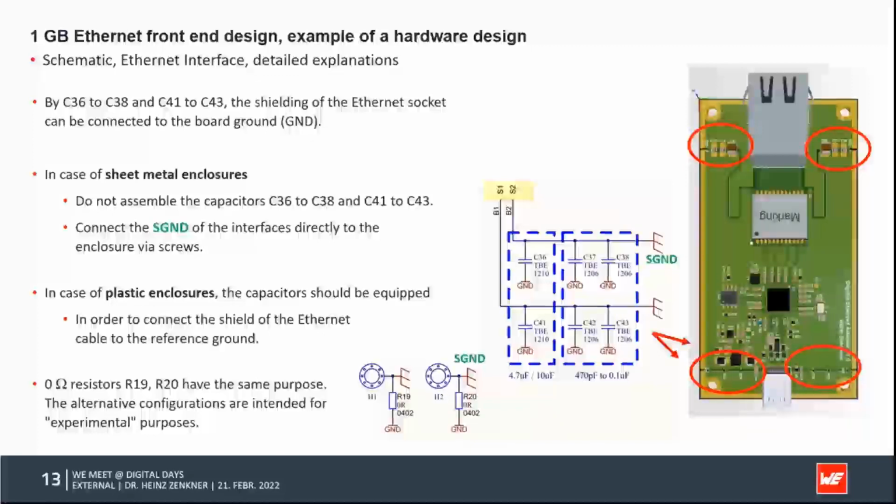Then you have a much higher immunity against, let's say, transients which are coupled in from the cable to the port, or from the other side, depending on how long the USB cable is. You can separate transients which are coupled into that cable.